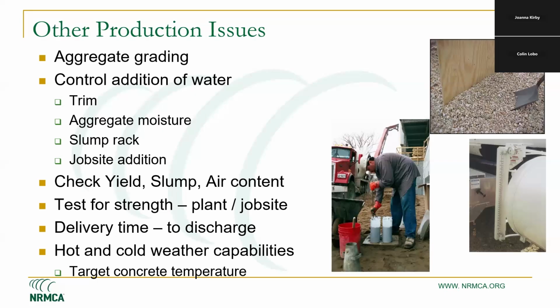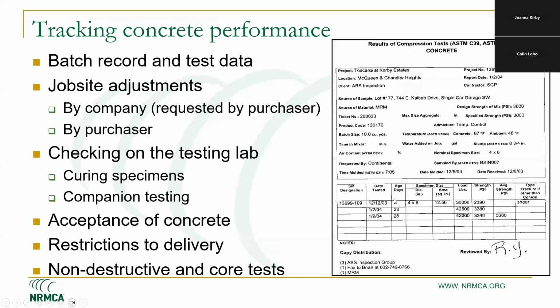Things vary in summer and winter, and you may have to make adjustments with seasonal changes to your concrete mixtures in terms of admixture quantities and other adjustments to manage concrete at different temperatures. The other aspect is to track your concrete performance. These are some of the factors that you may need to look at.